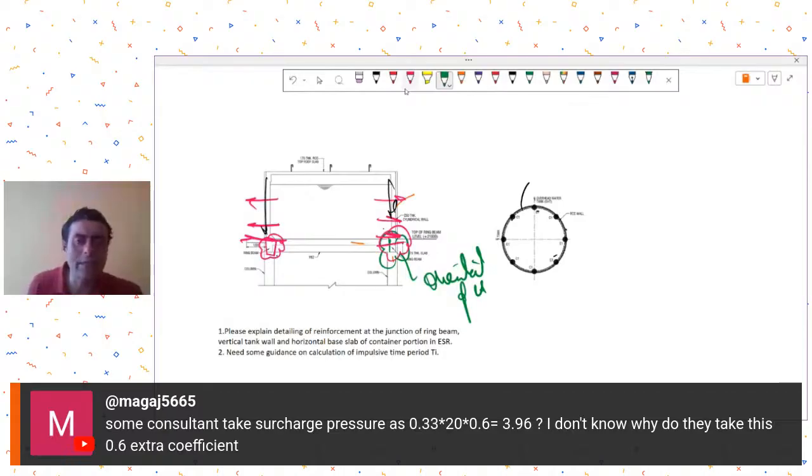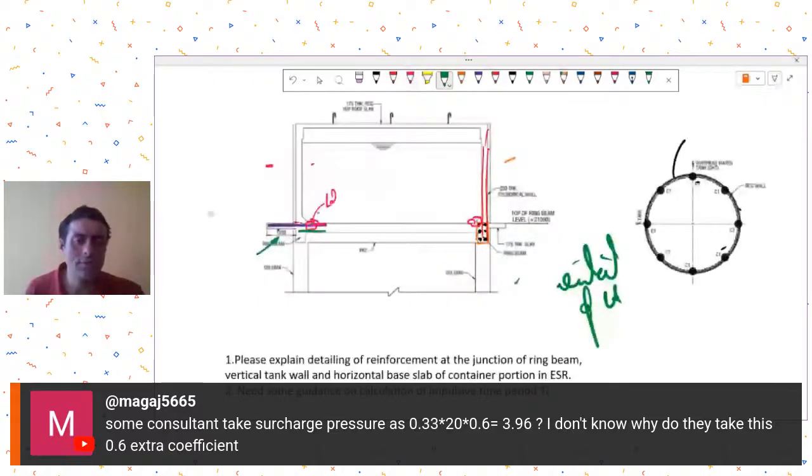See, if this cantilever is at the same level, you may be tempted to provide a bar like this. But then what happens is that now you have provided adequate development to the horizontal slab bar. So you just check, then in that case, maybe don't provide any releases, etc., and just try to continue this bar. If you're continuing this bar for the cantilever, then do not provide any releases, etc., and just have a rigid connection over here.